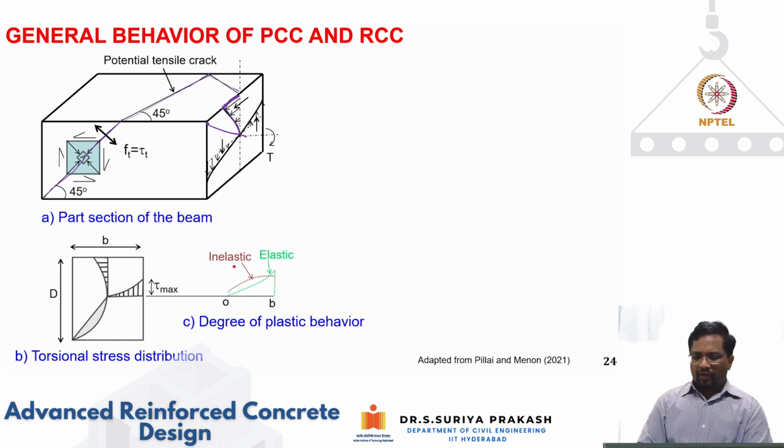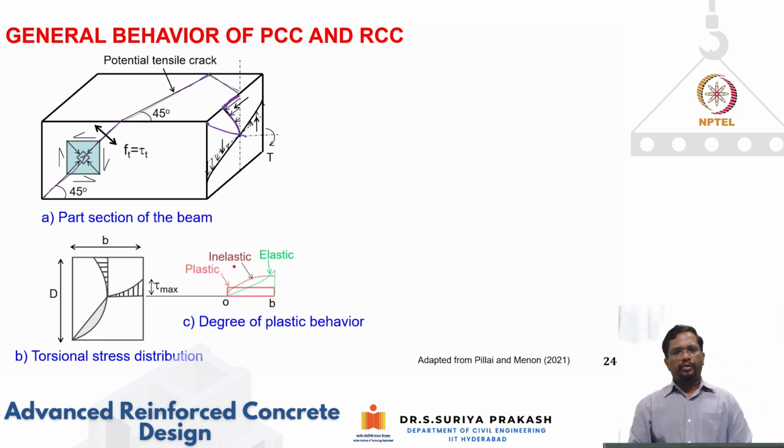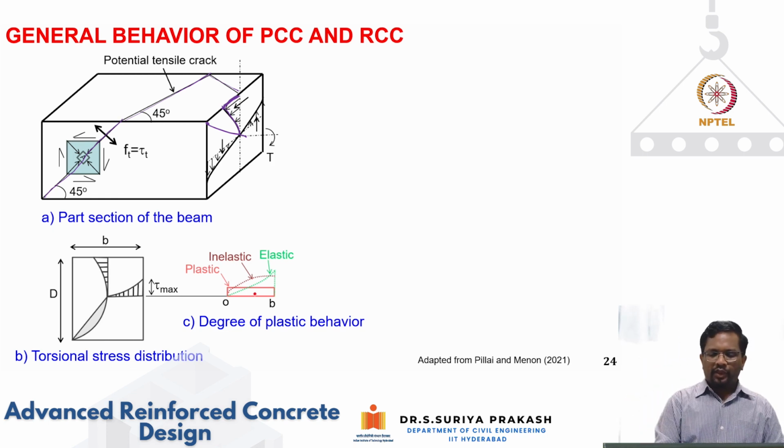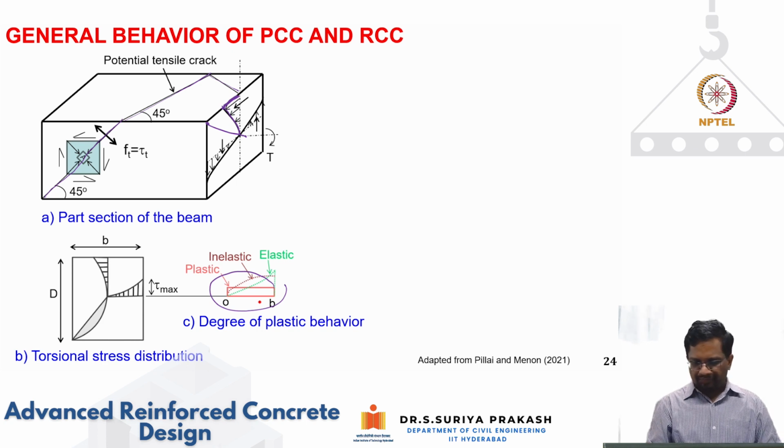Or sometimes, to simplify, what people do is, anyway, we are putting a lot of reinforcement, and after cracking the material becomes inelastic. So I can simplify it as plastic behavior, assuming that everywhere I'm going to have the same shear stress. So you can model it any way. People have come up with different theories, either assuming elastic behavior, inelastic behavior or plastic behavior.